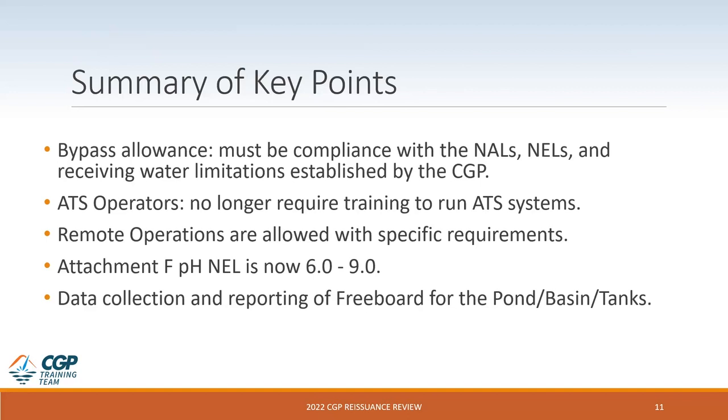Remote operations are allowed with very specific requirements. And there is now an NEL for pH included in Attachment F. And the data collection and reporting of freeboard for the pond, tank, or basin system is now required to be read, recorded, and reported every 30 days.